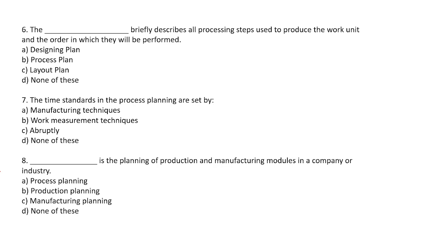Those four, along with digit 5, auxiliary holes or gear teeth, are the primary code. Digits 6 to 9 are the secondary code, where digit 6 tells the diameter and length of the workpiece. Digit 7 is the material used. Digit 8 is the shape of raw material, such as round bar, sheet metal, casting, etc. And digit 9 is workpiece accuracy. So this is the main interpretation of the nine-digit workpiece coding system.